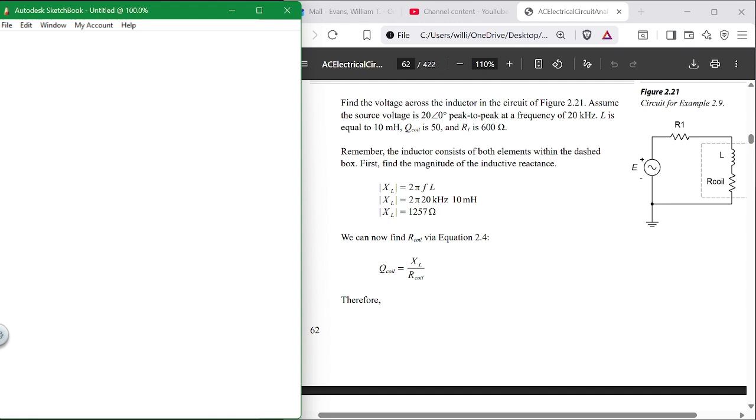So you can flat out measure an inductor. You can put it across an ohm meter and measure for resistance, but then you have to put it on an inductance testing machine to test it for its L value. In other words, if you pick up an inductor and you don't know what it is, you can't put an ohm meter across it and test it. You can get this value, but you can't find this value.